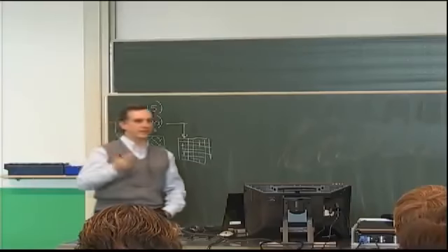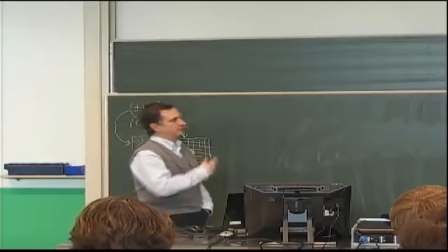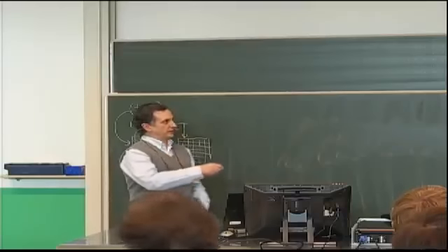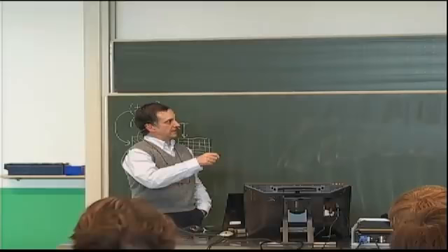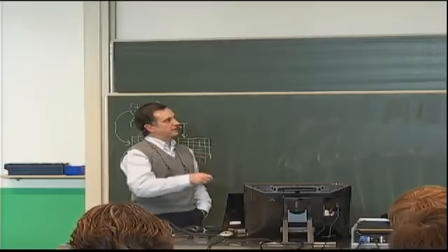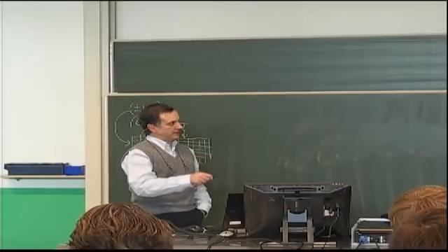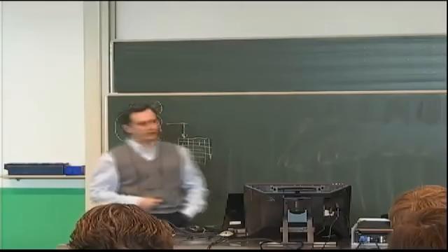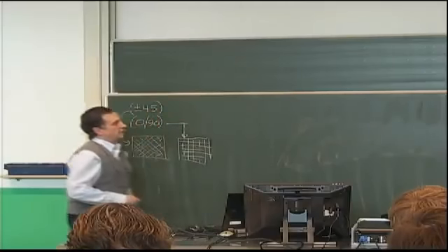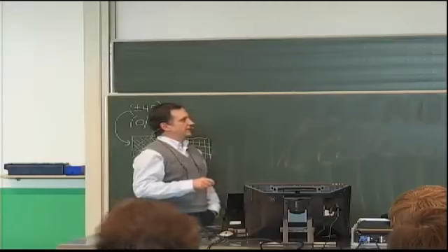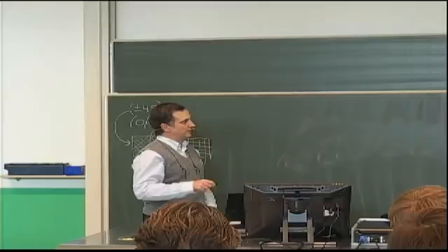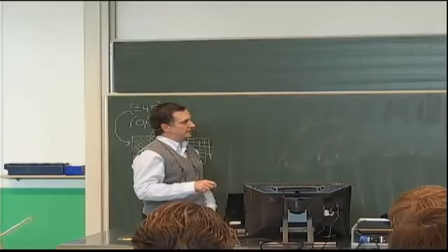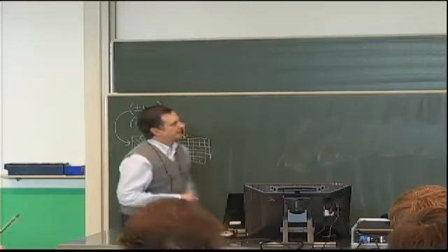So if you want to think of it as a stress concentration factor, feel free. The point is that the maximum stress is at the point of action of this concentrated force. And in this case, it is about 8.5 times the constant average stress far field away from the point of action. If you look at the results, the ones calculated with our methods with infinite series are very close to the finite element, with small differences in this region here.